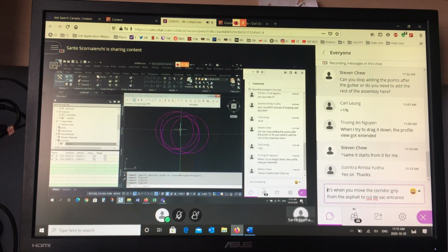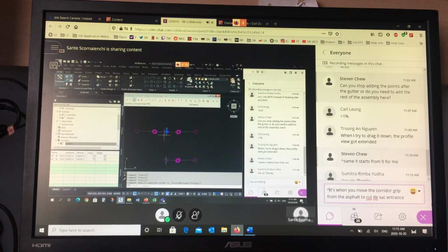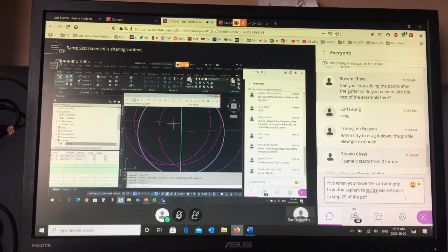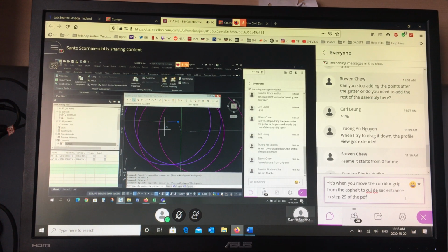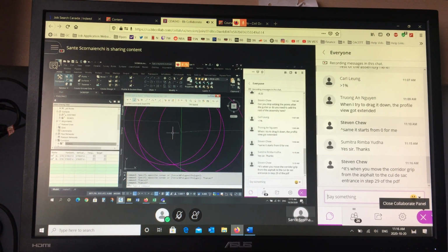Remember over here, the alignment is in the center of the road, so I build everything according to that being the center of the road. Then in this one here, the alignment is the gutter, so I build everything understanding that that represents the gutter. In your case, this green line would be right here, the back of curb, and then you have to create everything accordingly. So the widths would be the same, but maybe your slopes might be plus instead of minus.